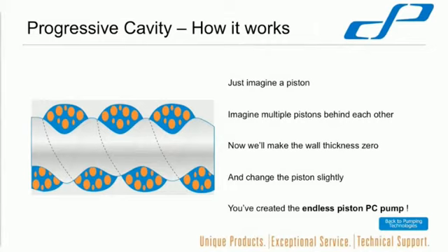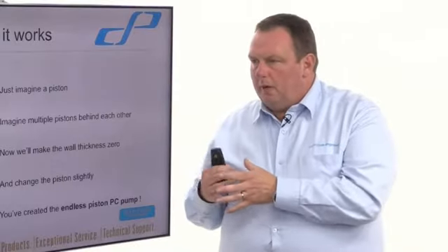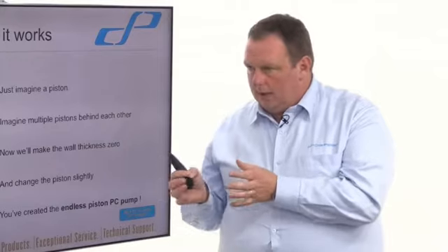Now, when we talk about what liquids we would pump with it and how we would do it, we can achieve good flow rates with these pumps. We can go up to 4-inch, 6-inch connections on them. You can get some very big pumps. Within the pumping world, we talk about NB connections as a way of defining it, although they go down to, I think, 1/2 inch is the smallest.